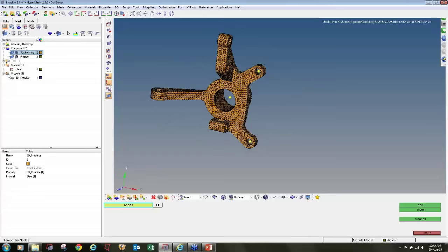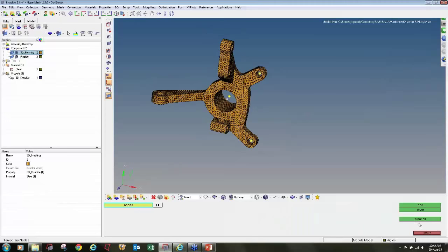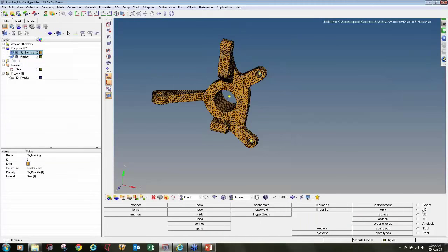Here I am going to apply a constraint. This one is constraint, so I will highlight this. So this side constraint, this side constraint. Here apply the torque in the opposite direction, and here I will apply the lateral forces and bump forces. So I will create the rigids first before applying the forces.